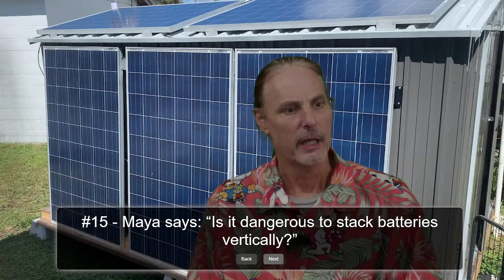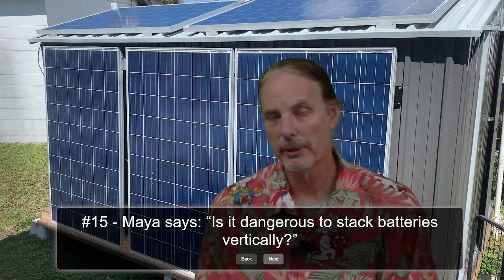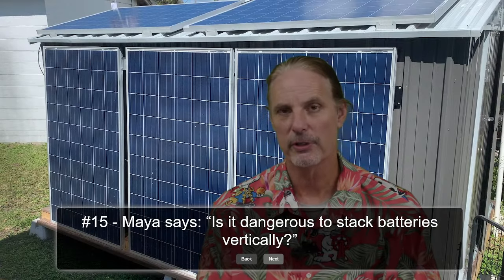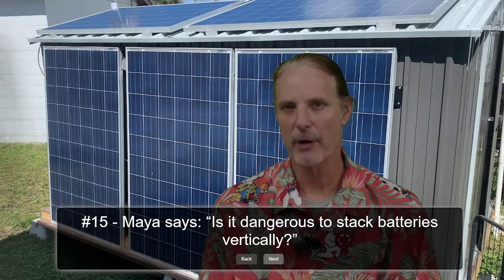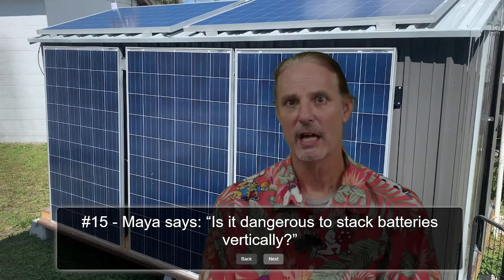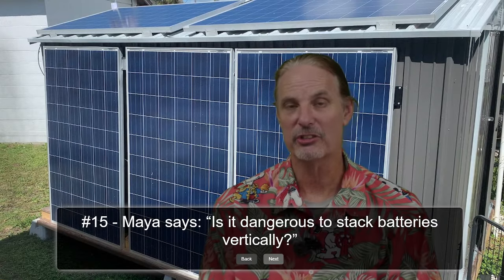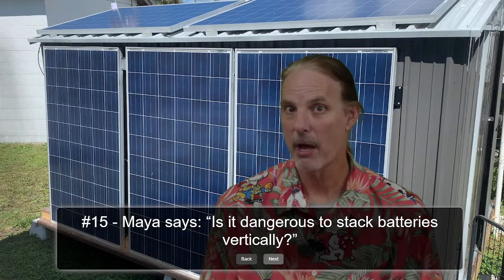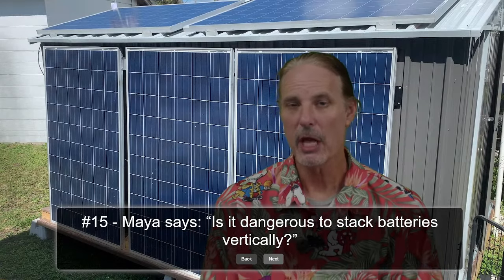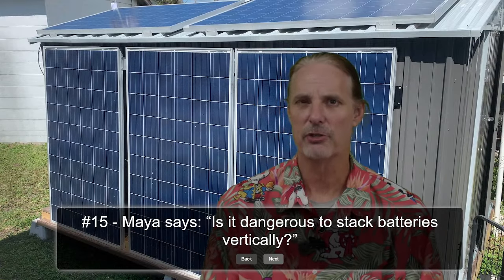Maya says it's dangerous to stack batteries vertically. I would agree it is dangerous to stack batteries vertically unless, the specs for each battery will tell you how they can be laid. I do have batteries stacked vertically in a rack. They're made for that. Rack mount batteries are made to be stacked vertically, but if you are just stacking them one on top of each other, I would check the manufacturer specs on that.